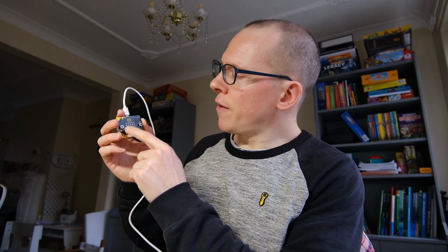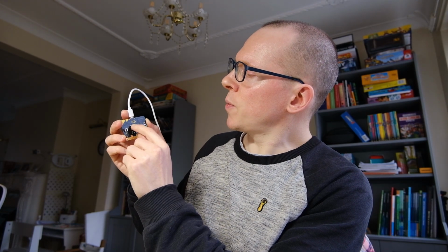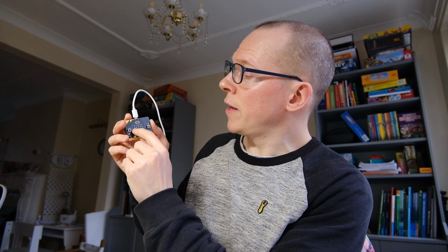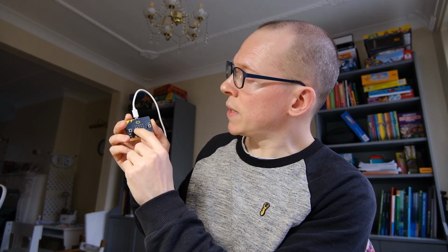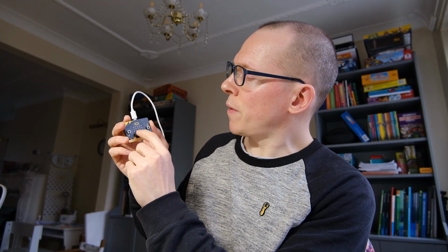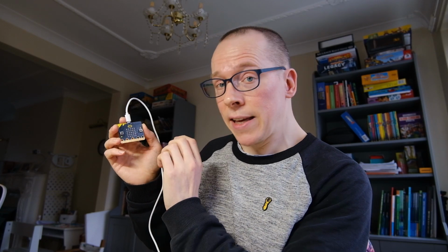There are 25 LEDs, and the way that I'm going to refer to them in the array is just as we've got the first one, second, third, fourth, fifth. So we have a row of 5. And then on the second row, we're going to have number 6, 7, 8, 9, 10. And then on the next row, 11, 12, 13, 14, 15, and so on up to 25. So in the array, we can easily store a piece of information about every LED. And that will be, should the LED be on or should it be off?